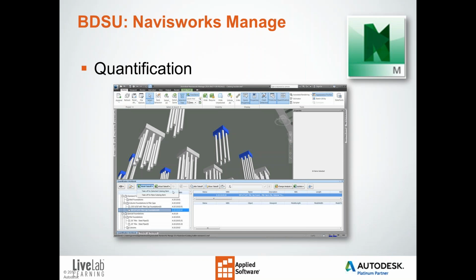In addition, I can tie quantification data to the model objects that are without properties. This ability to go from virtually no detail to high-level detailed models still allows more accurate quantity takeoffs. So I can do my manual takeoffs as I've done traditionally with 2D PDF sheets, or I can take advantage of the model takeoff and do automated takeoffs from object parameters. I can do automated takeoffs from model objects, or I can do a virtual takeoff for non-modeled objects.